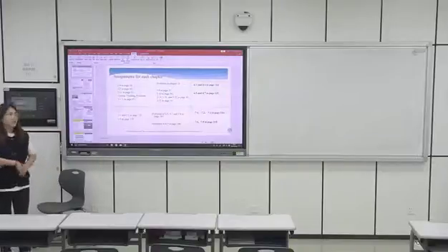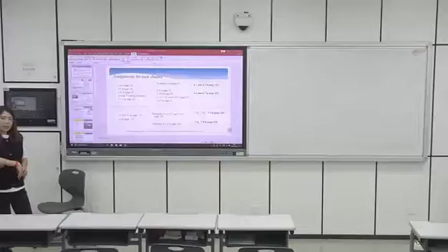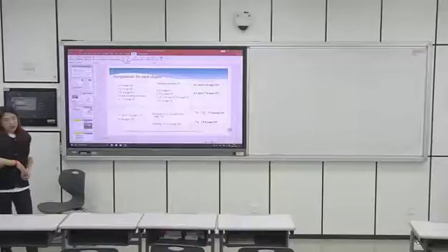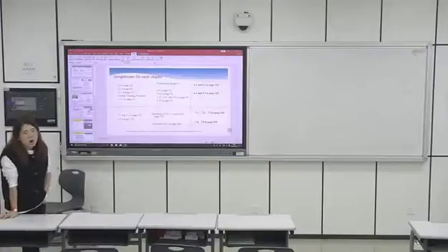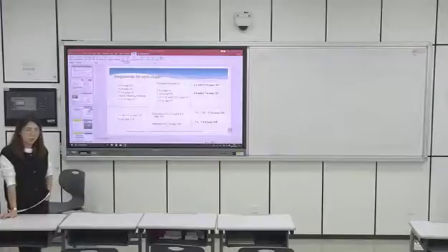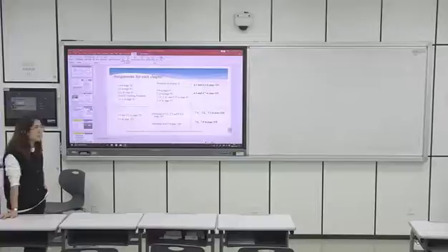And what is water content? Water content is actually a weight relationship. It is the ratio between the weight of water and the solids' weight, right? Try to remember, right? It is the ratio between the weight of water and the weight of solids. So this is water content. Degree of saturation is how much of the water volume to all of the volume of voids, right? That is saturation degree.